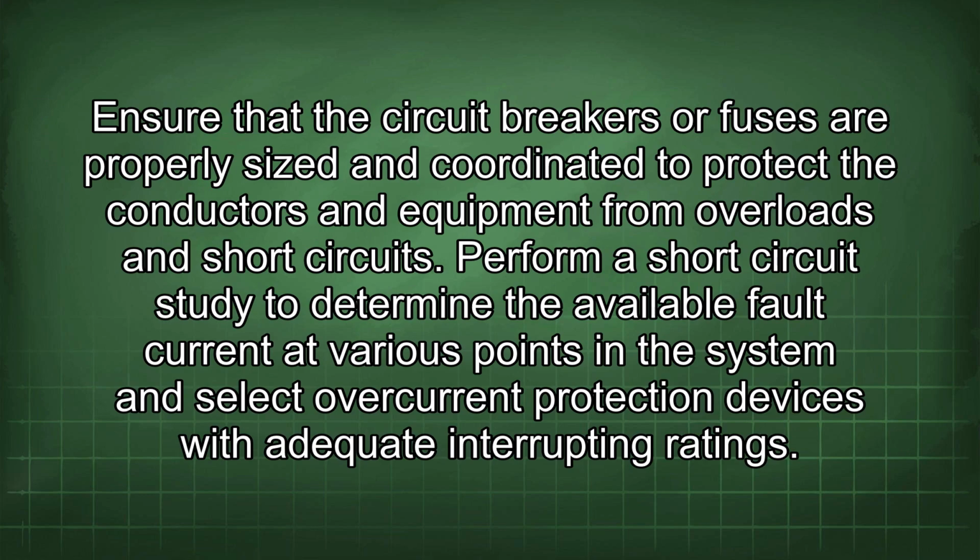Finally, consider the coordination of overcurrent protection devices. Ensure that the circuit breakers or fuses are properly sized and coordinated to protect the conductors and equipment from overloads and short circuits. Perform a short circuit study to determine the available fault current at various points in the system and select overcurrent protection devices with adequate interrupting ratings.